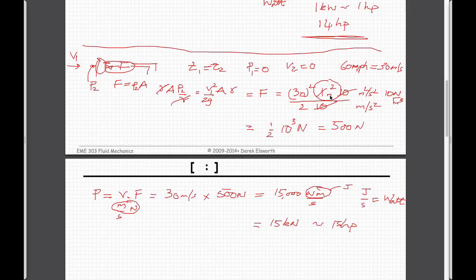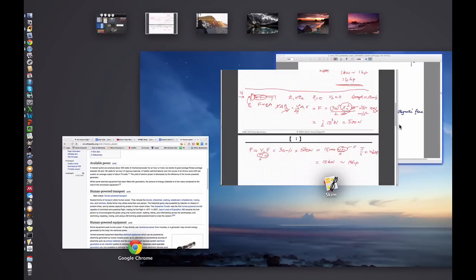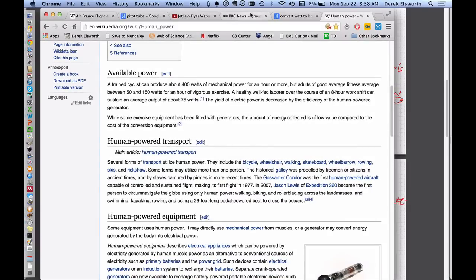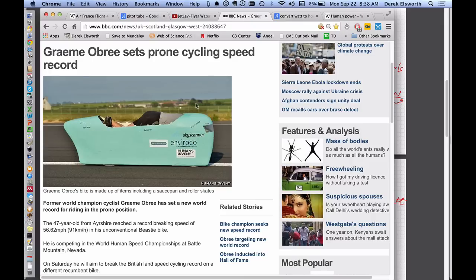And it's not accounting for the fact that it's streamlined. He's not pushing a 1 meter by 1 meter slab in front of him. He's got this kind of fancy bicycle that he is ergonomically lying down on, and it's moving ahead at some relatively small frontal area. And I guess that's his butt, isn't it? I guess that's his face down here. And it's streamlined. It's got this trailing edge here to stop eddies forming and sucking you back, in terms of being aerodynamically efficient. So those are useful calculations to be able to do.